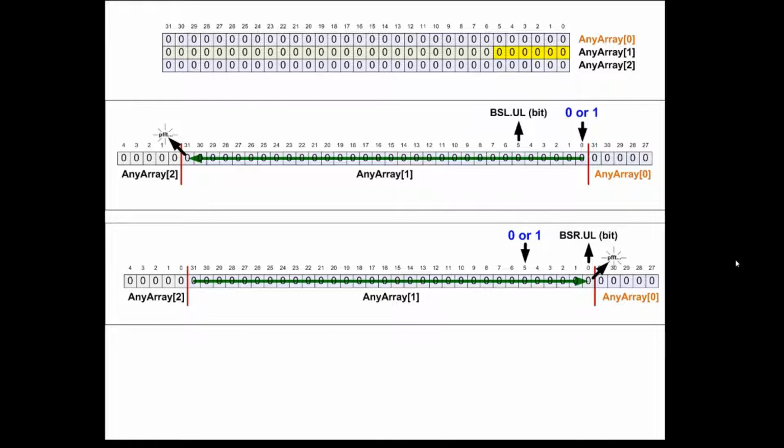Now that value that's in bit 5, when it gets unloaded to the unload bit, it also shifts to bit 6. And as you keep executing the bit shift left, pulling in new values at 0, unloading them at 5, they don't disappear; instead they go to 6, 7, 8, 9, all the way down to the end. And when they get to the limit of that element, of that array, then off into bit space they go.